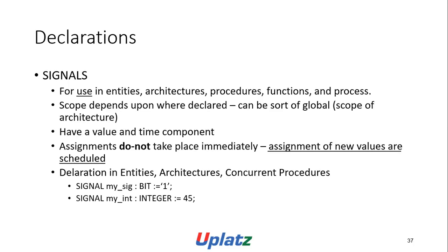Declaration of signals: for use in entities, architectures, procedures, functions, and processes. Scope depends upon where they are declared; it can be the global scope of the architecture. Signals have a value and a time component. Assignments do not take place immediately. Assignment of new values is scheduled.